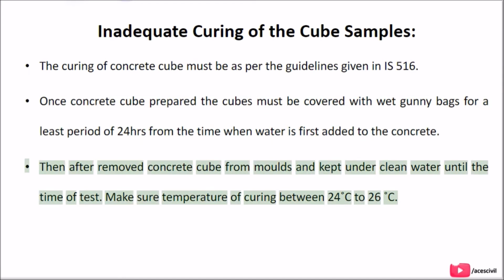Then remove the concrete cubes from the molds and keep them under clean water until the time of test. Make sure the curing temperature is between 24 and 26 degrees Celsius.